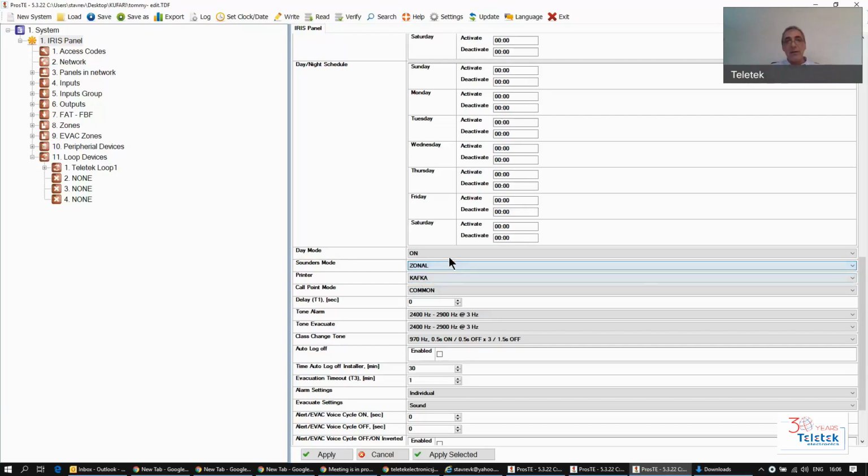In that respect, if I get fire detectors announcing fire or going into fire state in a zone, and the sounders are set to zonal, the sounders from this zone will turn on after the delay you specified previously in the zone. But if you press a call point that is set up to zonal, the difference is that the call point will bypass the previously set delays for that zone. Delays referring to sounders action. That's why I'm saying they kind of go hand in hand.